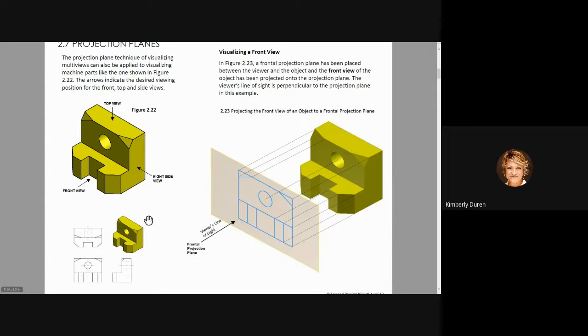Now, I'm going to tell you what a feature is. Everybody heads up. A feature is something you can touch. I can touch this plane. A plane is a feature. A hole is a feature. This plane or this notch, these surfaces are features. Features are described as something that you can touch. All right, so every feature, every place I can touch, I need to dimension it to its true size when I'm looking at it in the correct view to get that size.